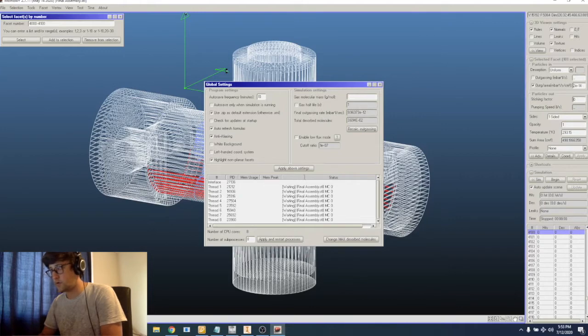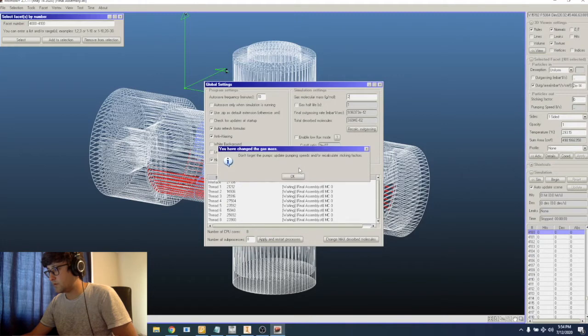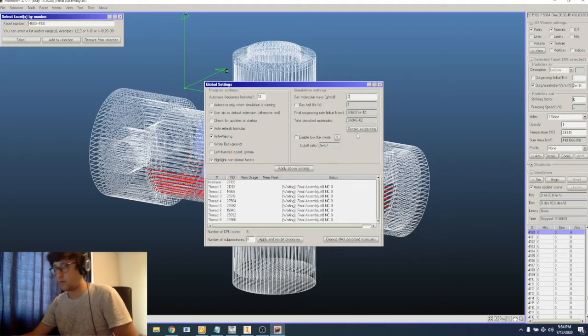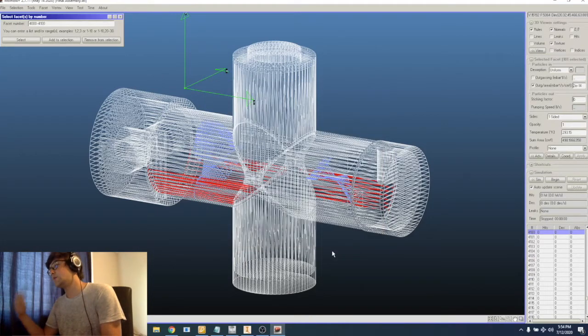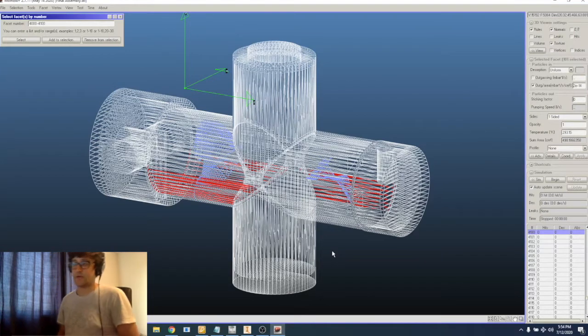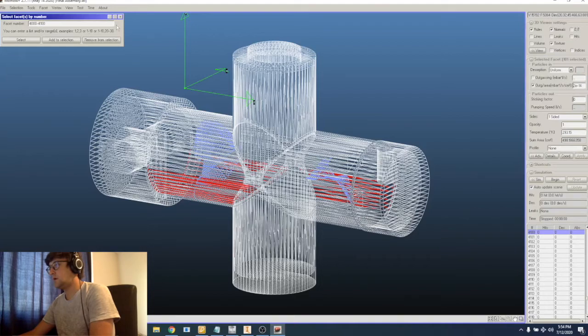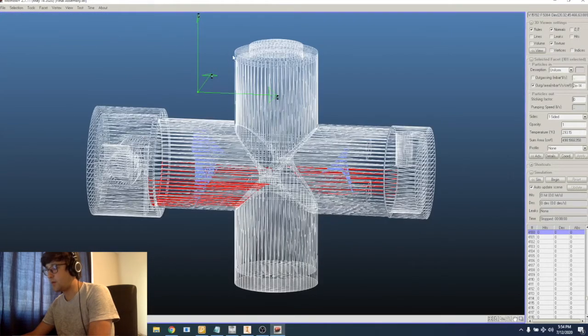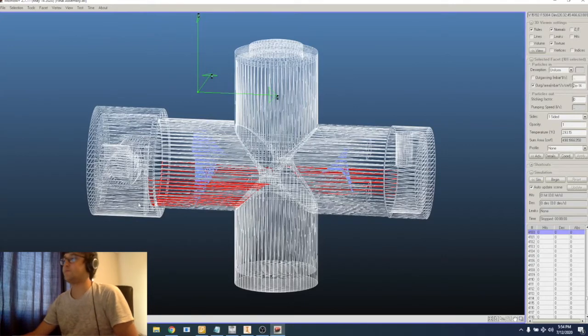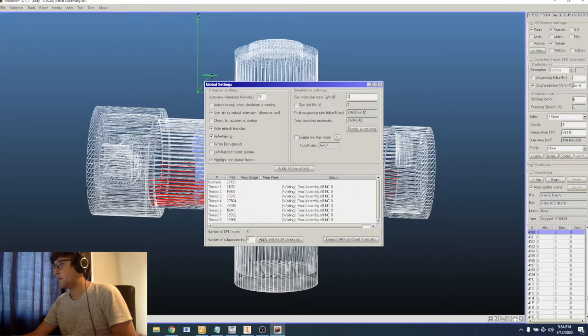You could do hydrogen, which is going to be a better representation of what's actually at ultra high vacuum. So there's really not much nitrogen at all. So, okay. Now I have something pumping, I have something outgassing, and I have some textures enabled, and I changed the gas molecule to the correct gas molecule that I want.